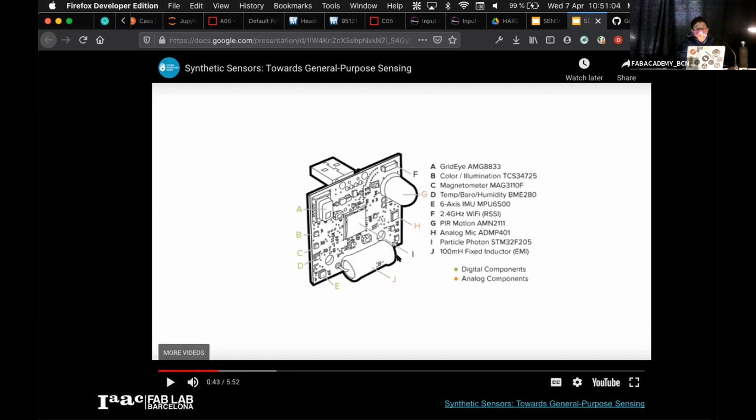That we don't know, but it's not only that. Also, this sensor or this PCB is not only that. Another thing that we're going to talk about is how many computers do we need to do this? Do we just need a small microcontroller? At the end, these sensors are going to spend very little energy. We're going to be talking about less than 20 milliamps, less than 50 milliamps normally. A sensor that consumes more than that is really weird, needs a fan or needs something big. And these sensors don't look like that.